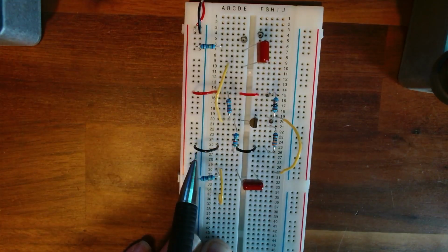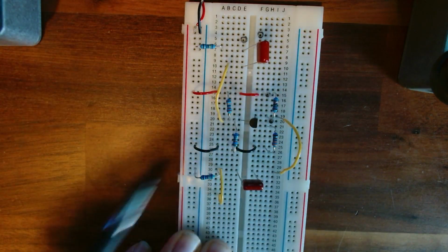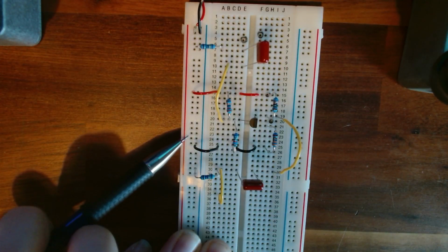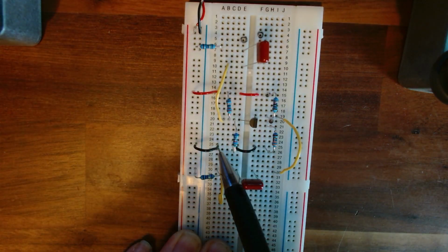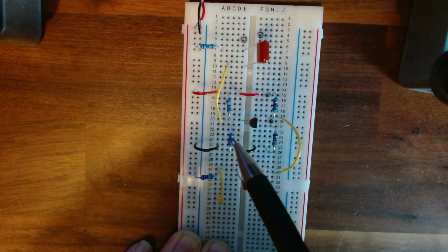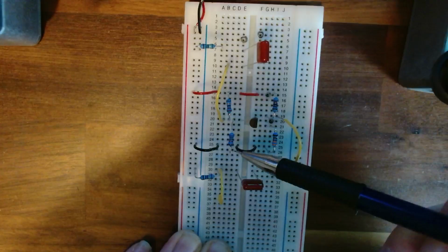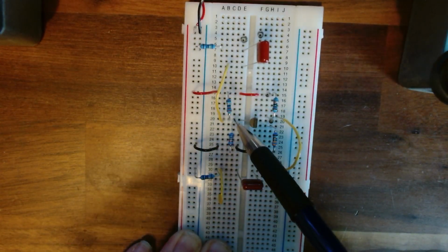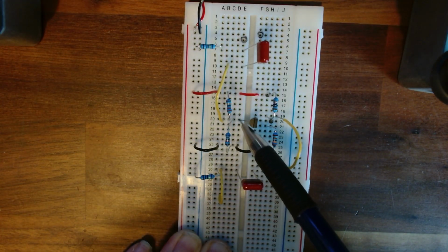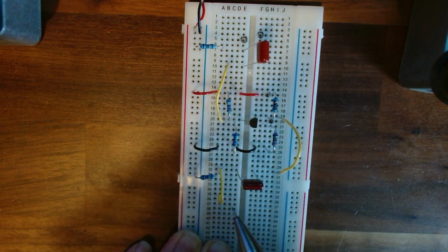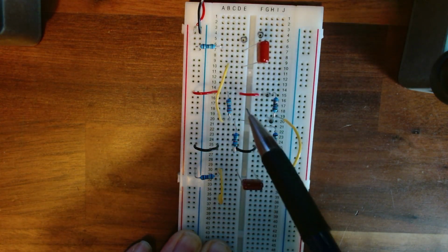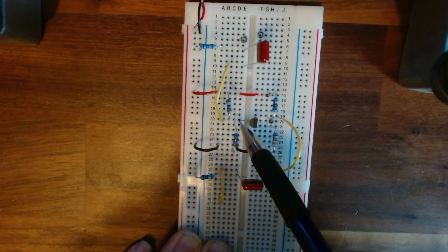And then again, I've got a black wire here for our ground. Just note that it's going into the blue side of this strip and the red one's going into the red side. And it's joining into pin 25 there. And then this is our 68k resistor going from line 25 up to line 20 and joining the base pin 2 of our transistor, the 220k, and our signal, which goes back out to our input.